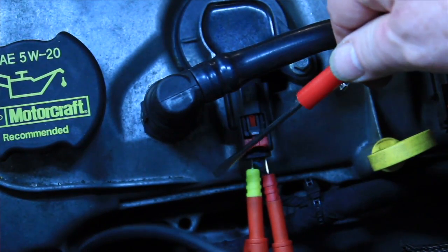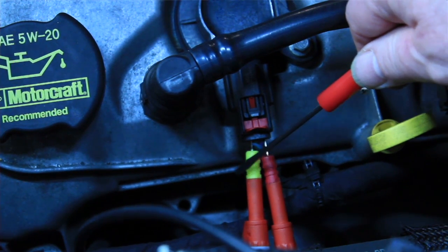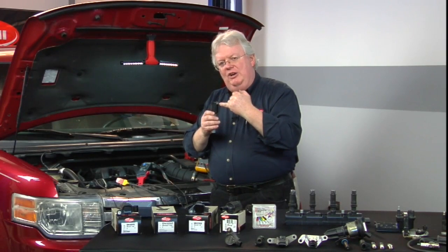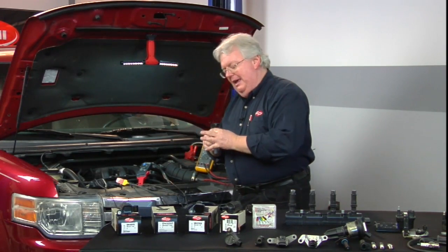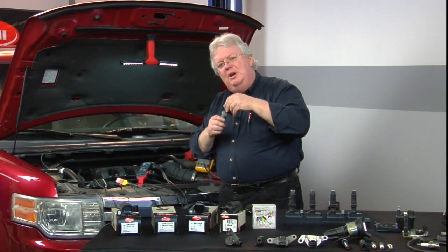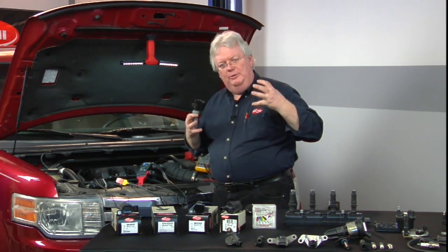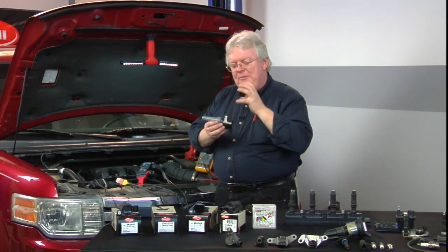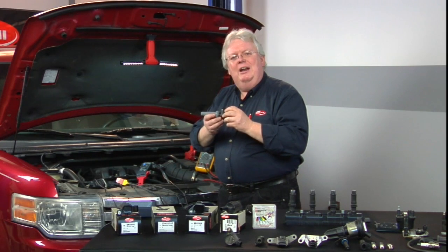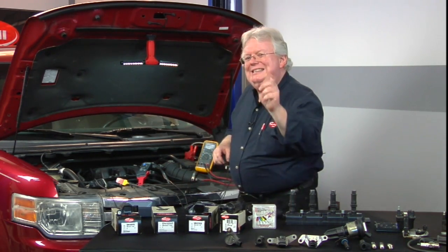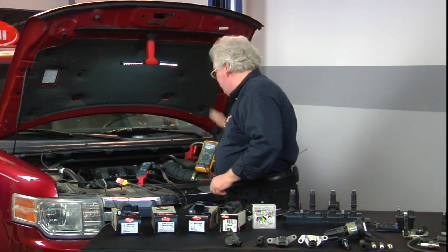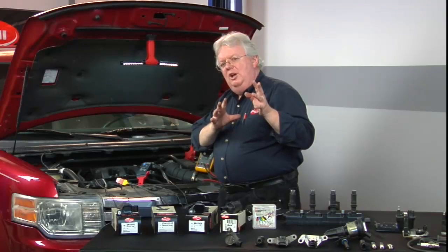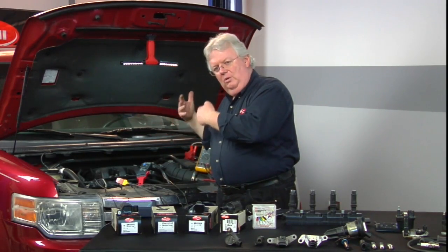Now, since we have a primary winding, which we actually are hooked into right here, power from the ignition fuse goes to one side of the winding, and a ground, when the PCM applies it, goes to the other side of the winding when we want the primary winding to saturate and build up a magnetic field, so we can then collapse it and create the self-inductance, which causes the mutual inductance of the much longer, larger secondary winding to make the spark. So what will we see between chassis ground with the meter? I've got my black lead on ground and the red wire going to the ignition coil. Let's go ahead and see.